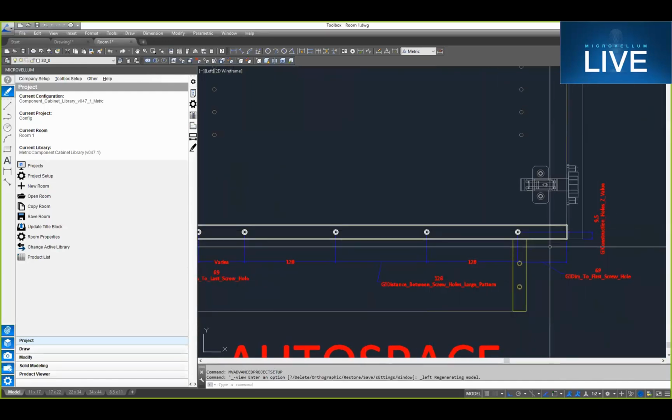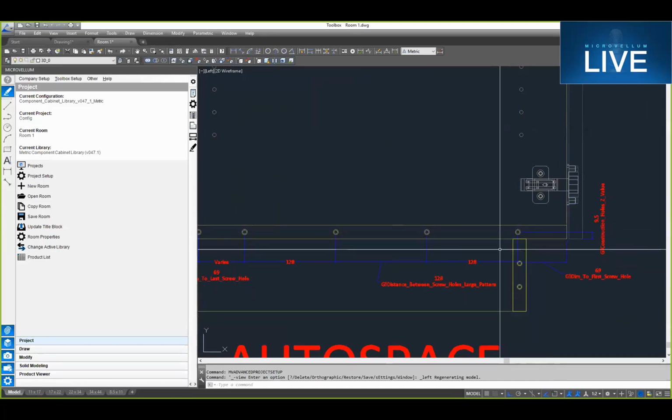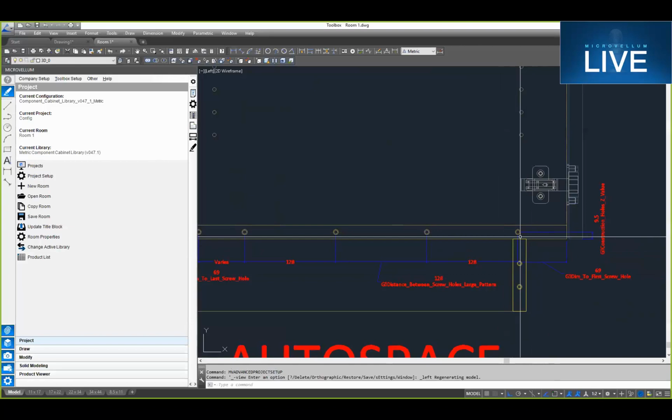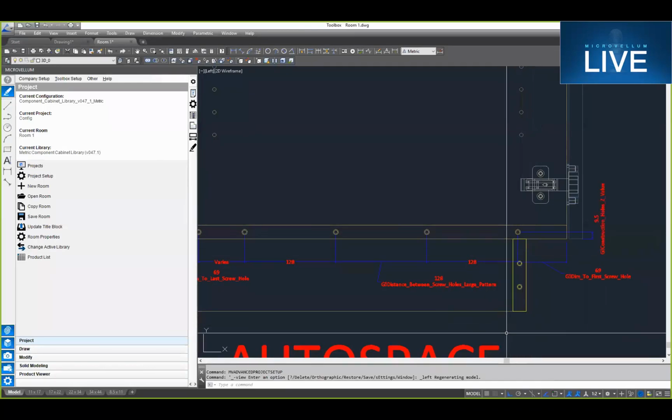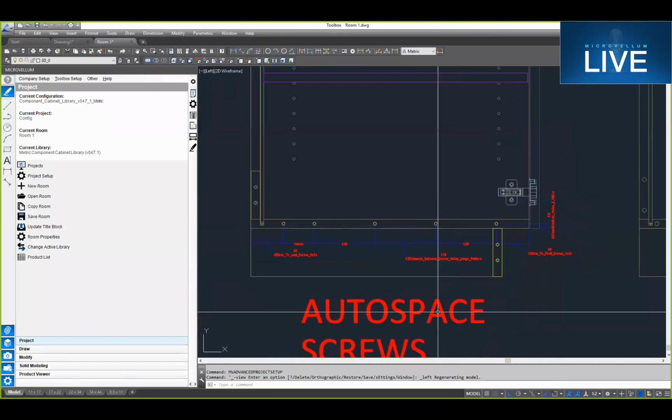You do have the option to specify the height off of the table as well. So if you're using a fixed head dowel machine, you always wanted to leave that at a specific dimension, then you could do that, or you can set it to center that hole on the thickness of the panel as well. And so if you have a CNC dowel machine, you want to make sure that's always centered, you can certainly do that in the construction holes Z value. Again, that's in the global variables there, and you're able to set those options within there.